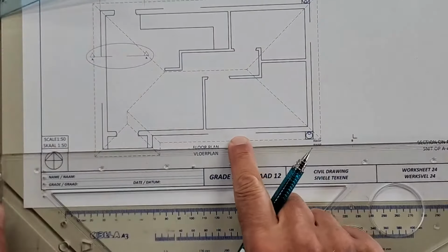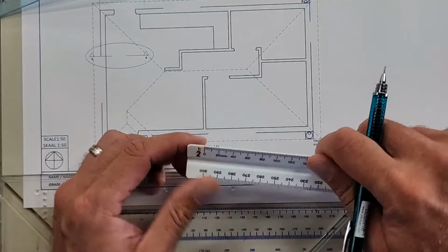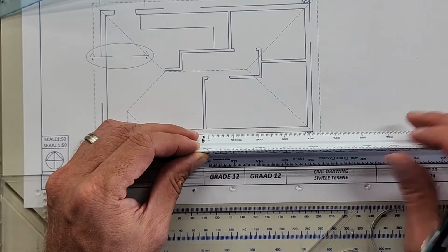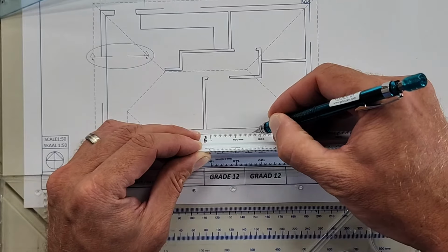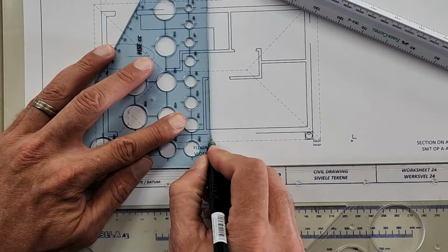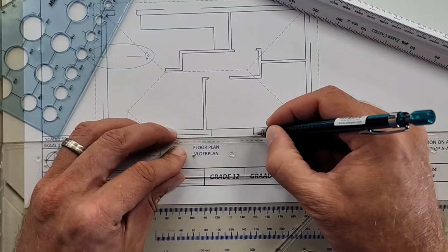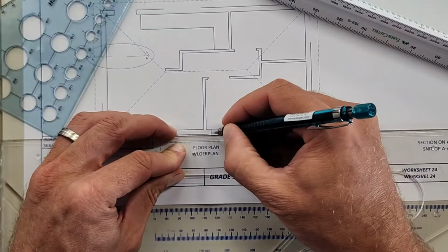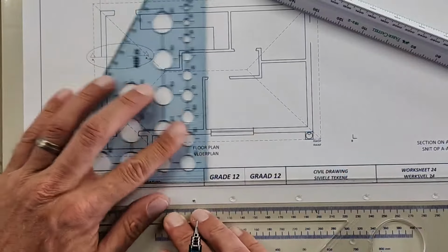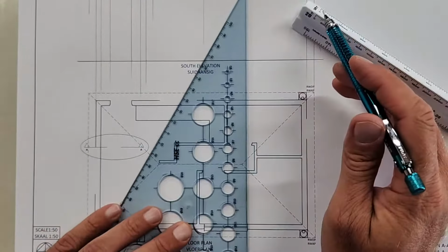Let's quickly do the window that goes in here. It's scale 1 to 50 and that window is W3, which is 1700. So just find your correct scale here. And that's 1700. So that's going to be, remember they're trying to catch you out. You're going to have to put that in the middle of this block. And I'll draw that in quickly. There's our window. And that gap there we will have to fill. There will always be a gap that they're checking that you do the pencil fill. And then in the middle of those walls, your 1 millimeter gap. And so it's that I'm going to project up for the window.